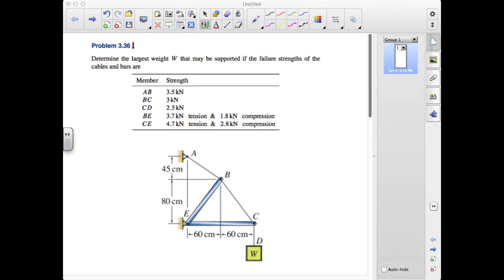Among these 5 elements, the one that's easiest to treat is the tension in member CD. If we choose to isolate the weight itself, then vertical equilibrium will give us that the tension in CD is equal to the weight. Where else should we focus our attention?